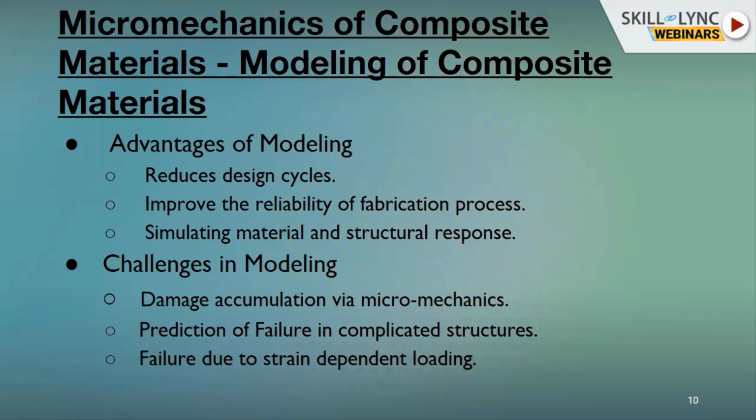The major challenge in modeling these composite materials is what the damage accumulation in the composite materials will be when you subject them to various loading conditions. This is very vital because the damage mechanism involved in composite materials is very different from traditional metals and alloys.